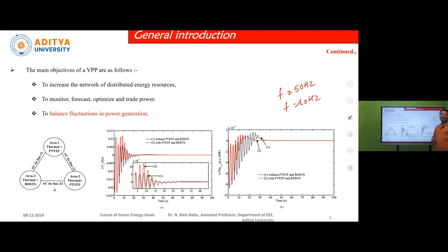During Diwali or during festival days, there will be a sudden rise in load consumption. Due to this sudden rise, our system may lose its frequency from 50 Hz to 49.5 or 49.14 or something like that. But with immediate effect, this frequency has to come back to the initial condition. This can be done by the load frequency control, that means the primary control of the AGC system. We can observe this, and that means to balance the power fluctuations. Balance in the sense that the amount of power being generated should be equal to power demand plus loss. This equation should be balanced.